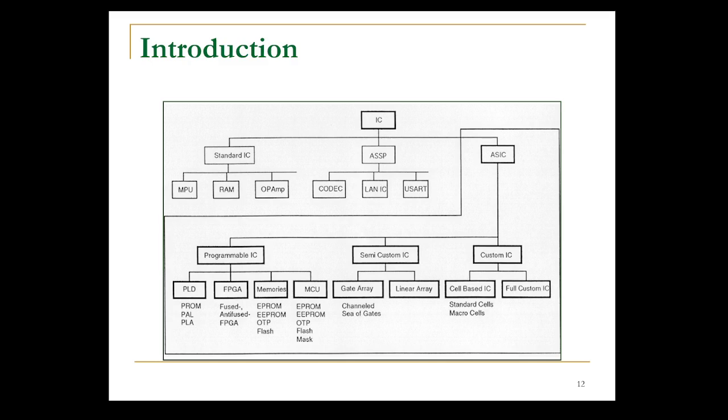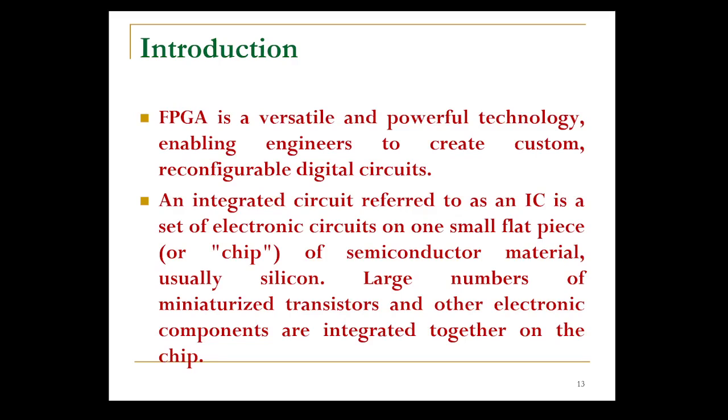EEPROM is electrically erasable programmable read-only memory, EPROM is erasable programmable read-only memory, OTP is one-time programmable, flash and mask. Semi-custom ICs have gate arrays, channeled gate arrays, sea of gates gate arrays, and linear arrays. Custom ICs, cell-based ICs have standard cells or macro cells, and full custom ICs. FPGA is a versatile and powerful technology.